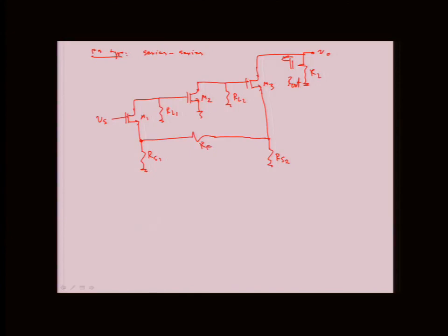I'm looking at how the feedback is getting passed, right? So the circuit produces current, and then the current terminates on some load and generates voltage. That's fine. But that voltage is not used anywhere back, right? So what is being used is this current quantity that passes down, right? So therefore, the feedback is series, right?